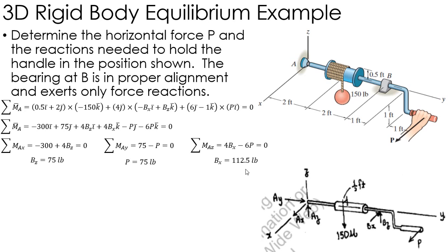Again, the best way to deal with it in 3 dimensions is to do the moments using the 3-dimensional cross product and then break it out, rather than trying to figure out which force creates which moment in what direction.